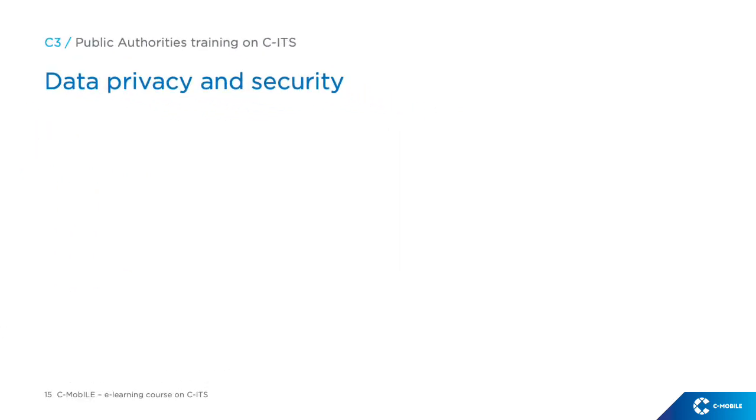As more vehicles equipped with C-ITS services hit the roads, software vulnerabilities become accessible to malicious hackers using cellular networks, Wi-Fi, and hardline connections to exploit them. The potential for hackers to gain unauthorized remote access to the vehicle network and compromise critical safety systems puts at risk not just users' personal information, but their physical safety as well. Such threats have created the need for broad-scale secure key management, supported by a public key infrastructure, PKI.